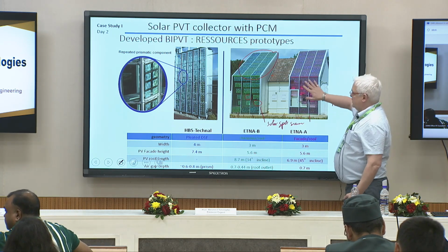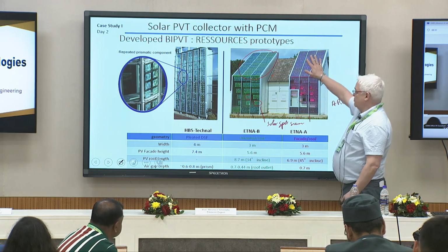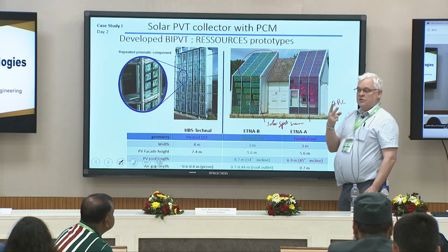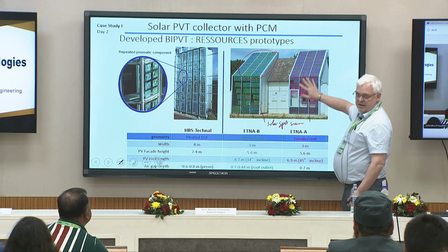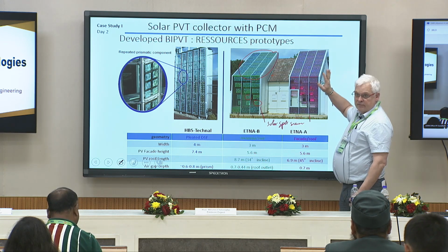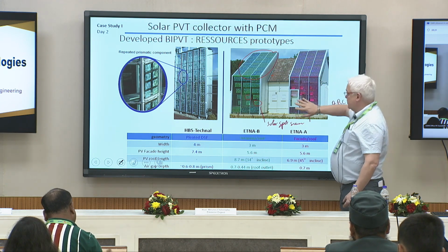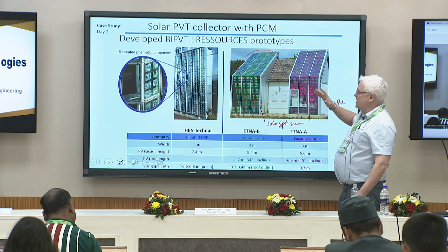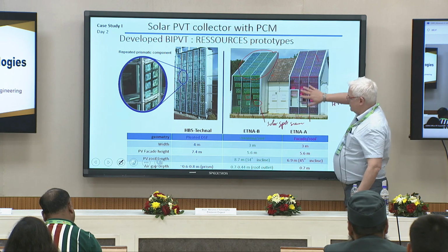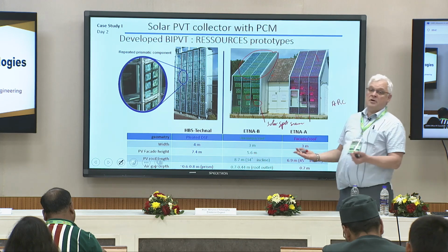Okay. And even if it was uniform here, and uniform here, you are at least obliged to have two inverters, because even if it is the same panel here and the same panel here, the inclination is different. So they will operate in different conditions, okay? So even if it was fully uniform, you can't put only one inverter for the whole installation. You have at least to have one inverter for this part and one inverter for the roof. Okay? It's a double inclination.